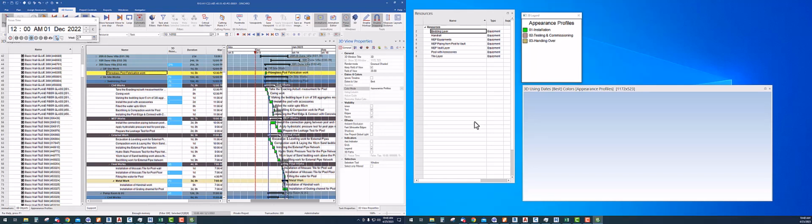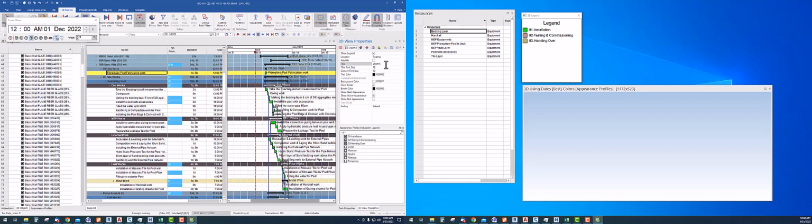Okay, so I am just pausing the video so that I can figure it out. By default it is taking auto title in the 3D view properties. So if I uncheck this, I can put the title here. Okay, so now it is showing legend. Now I will start recording. No, we need to add that legends into this. It will come later on.